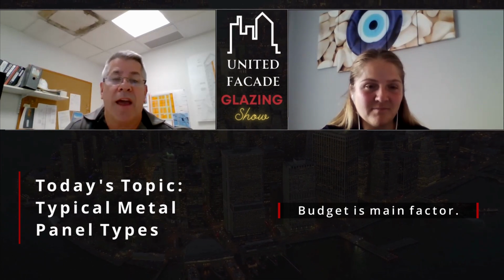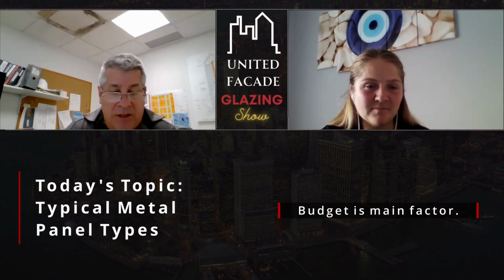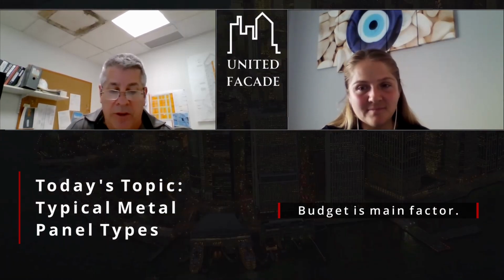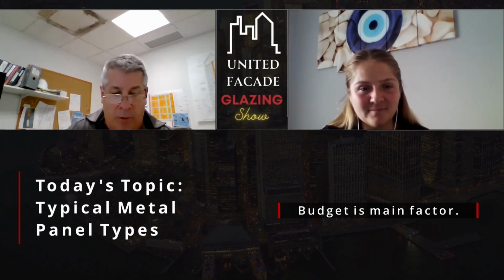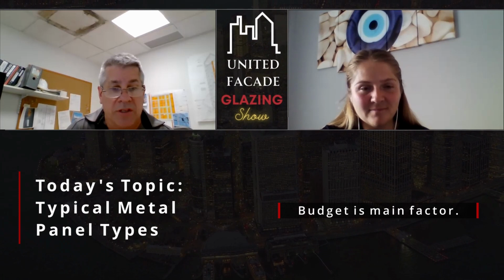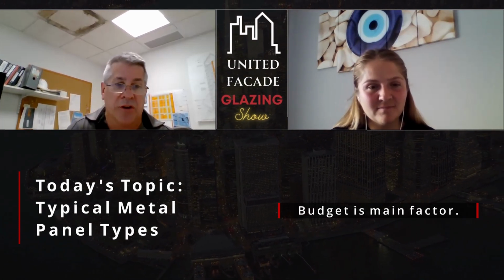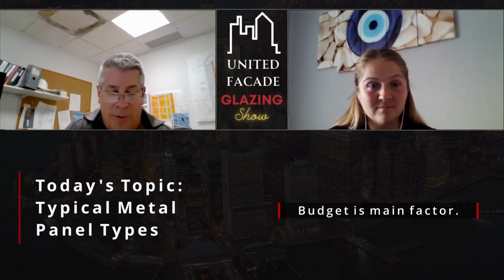They're both going to have a hanging system that has to be attached back to the structure. And it's just, the weight of the panel is going to be a big issue. So you need to understand, if it's going to be a plate panel, there's significantly more weight to it. So that sometimes is a big design issue to the engineers, saying how much weight they want hung off the side of their buildings.